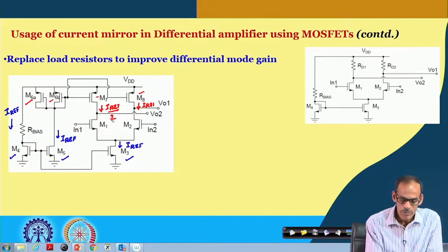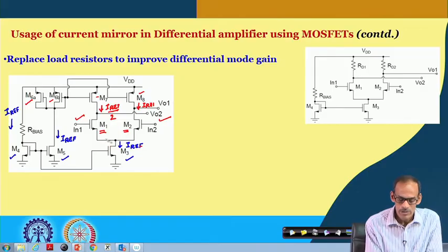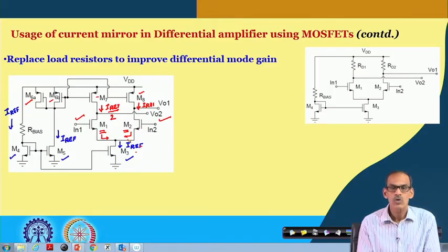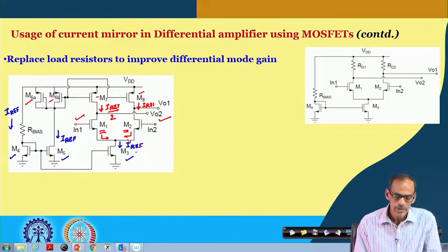Of course, this I reference current is in case we have the same DC voltage applied here, and if I consider M1 and M2 to be identical, that makes this I reference current get split into equal parts coming from M1 and M2, and everything is well balanced.